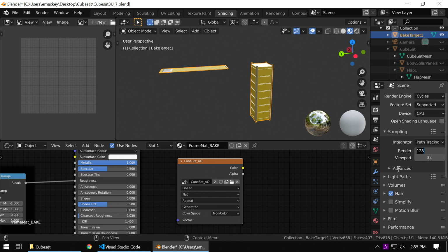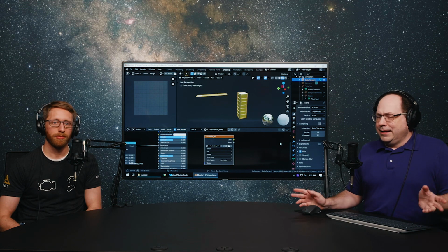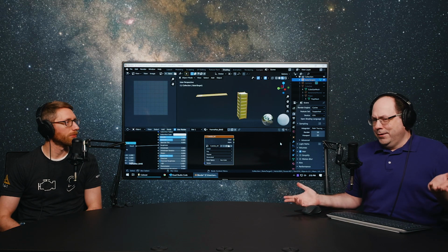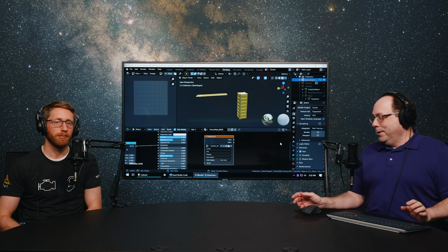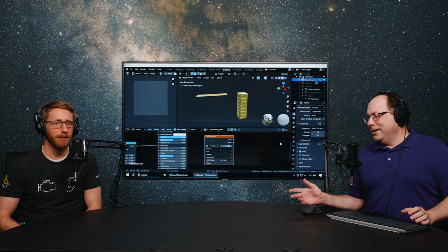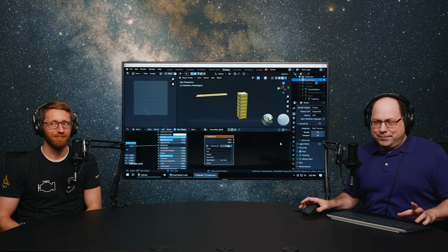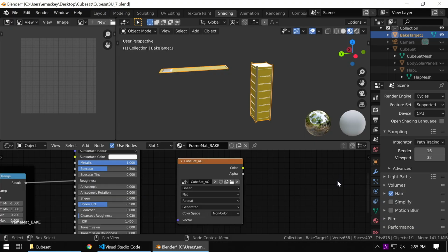The render rays are set to 128. I'm going to drop that all the way down to 16 because we are just doing a rough draft. I just want to get a draft render of this AO to see if, for example, I made some horrible mistake during the first modeling video. Unlikely, but still good practice. Just in the off chance that it happened and might be discovered later in the recording of this video, I will set this to draft mode.